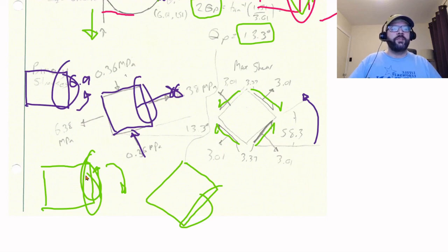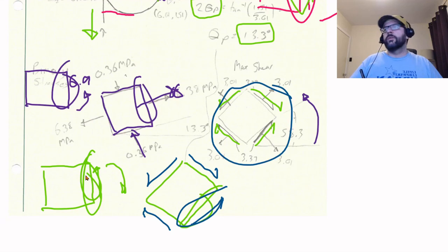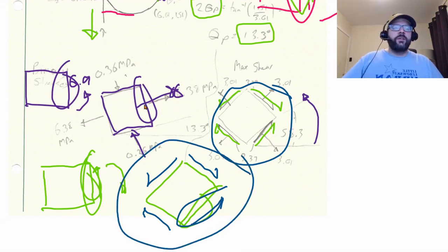So we'd still have the shear stress in this directionality on this face here, which of course means that we have stresses there, and stresses there, in order to keep everything balanced. Not too shockingly, it's the same result that we got if we had rotated 45 degrees the other way instead. So we got to the same result two different ways. And that is that.